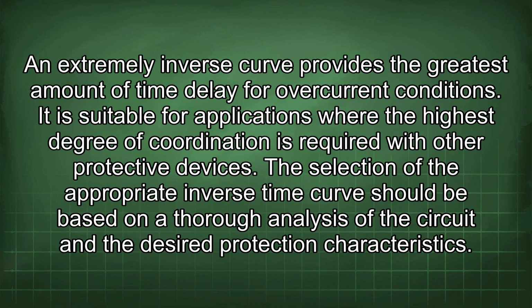An extremely inverse curve provides the greatest amount of time delay for overcurrent conditions. It is suitable for applications where the highest degree of coordination is required with other protective devices.